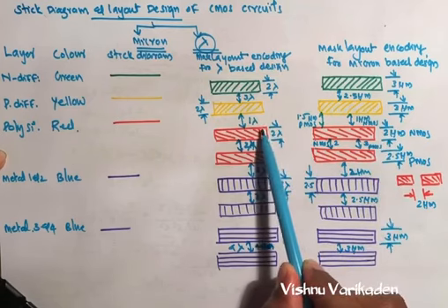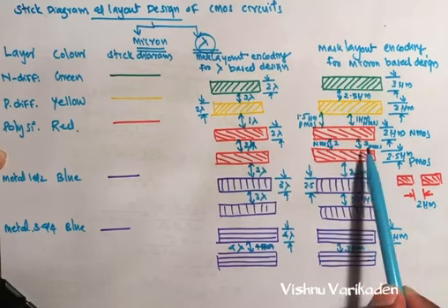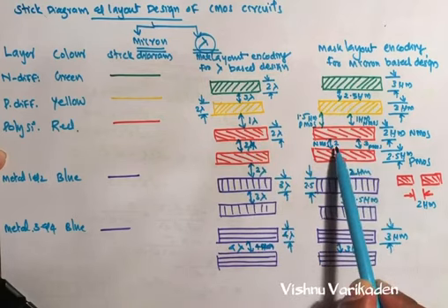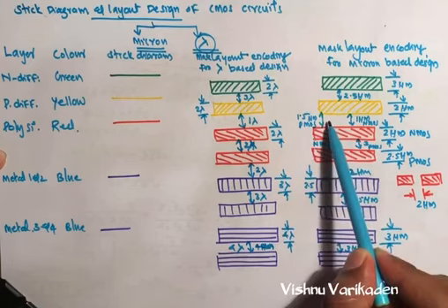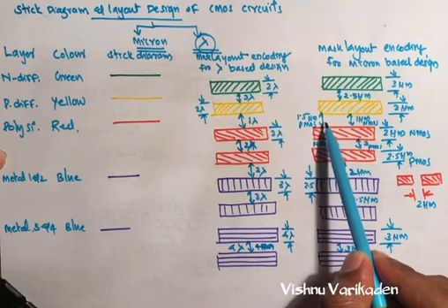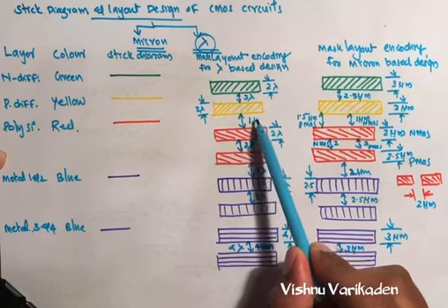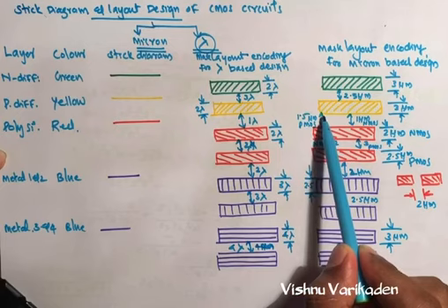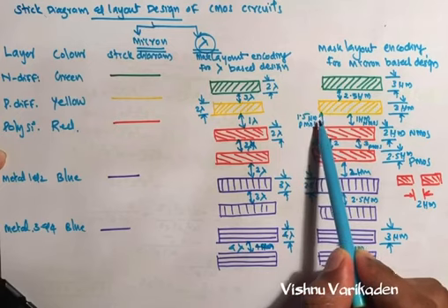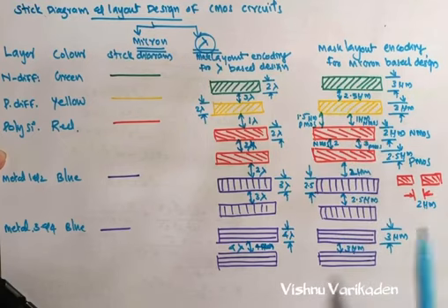So in between the polysilicon is 2 lambda. For this one it is going to be 2 for NMOS, 3 for PMOS. Also the polysilicon is coming between diffusion layers. So for N or P, the distance is 1 lambda. For micron based, for PMOS 1.5 and NMOS 1 micrometer only.